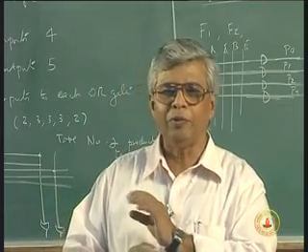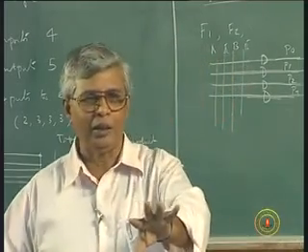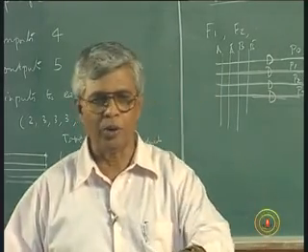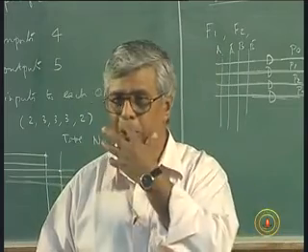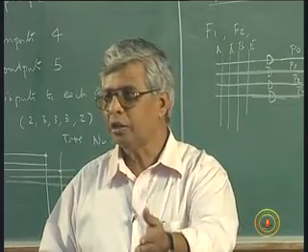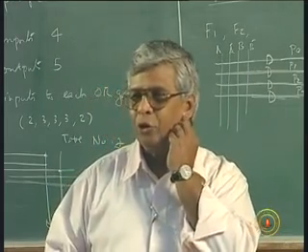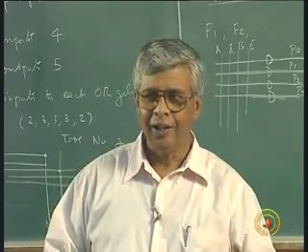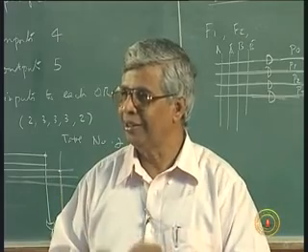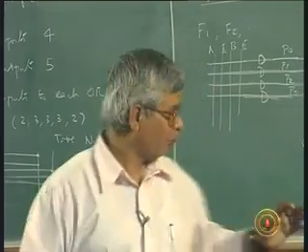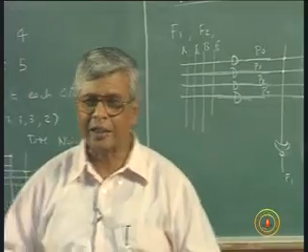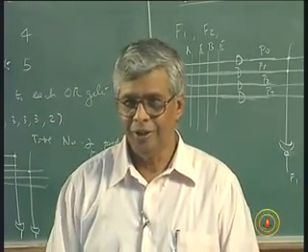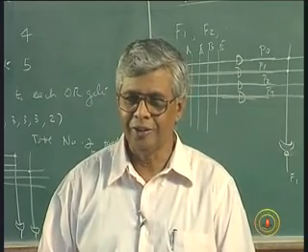So we want a chip in which I would trade off. I want 20 pins totally, 8 inputs, 8 outputs. You are having 12 inputs and 4 outputs. I want 12 inputs and 4 outputs, but you are having 8 inputs and 8 outputs. If I can trade off 4 of those outputs for inputs, that will be nice. I can do with the 20 pin IC and then be very happy about it. That is the concept of programmable I/O. So certain pins are designated as IOs. It can be used as input or output based on your requirement. It is a very interesting concept, right?